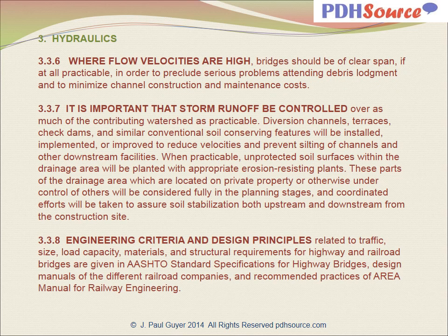Where flow velocities are high, bridges should be of clear span if at all practicable, in order to preclude serious problems attending debris lodgement and to minimize channel construction and maintenance costs.